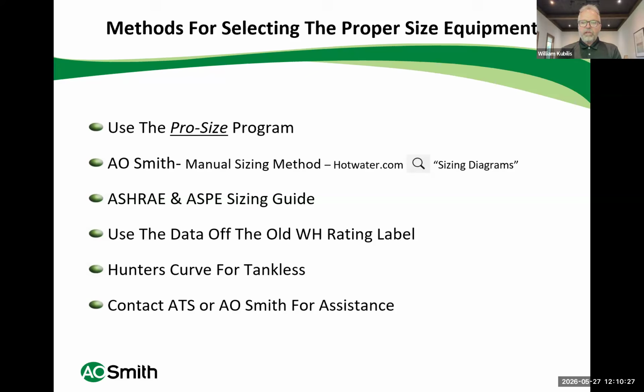You can also, like sizing a water heater, if it's an existing business and they're just updating their equipment, why not just go get the rating labels off the water heater and duplicate what they have? That's not necessarily the best because it may be undersized or oversized already, but generally, if the water heaters have performed well in the past, the new replacement ones of equal value should continue to perform as well.